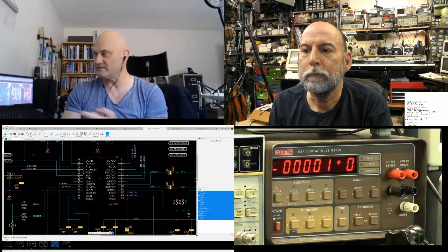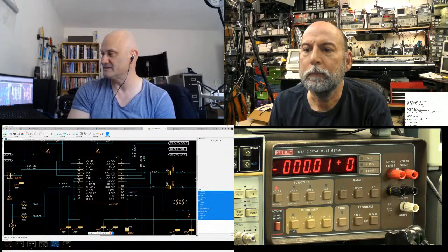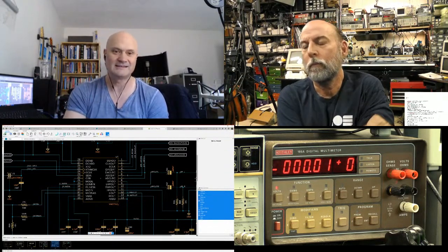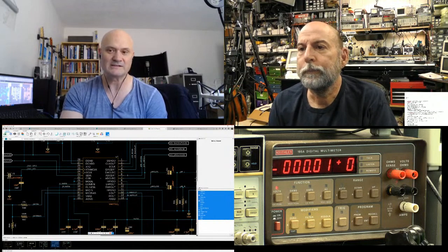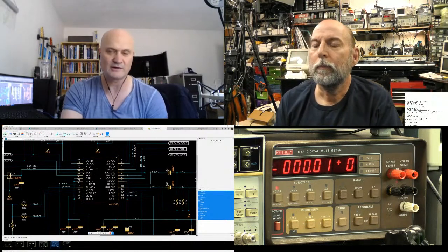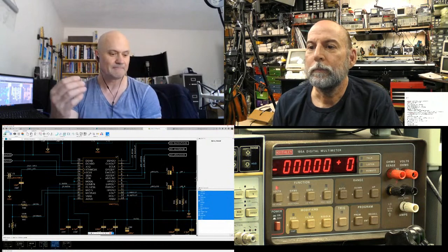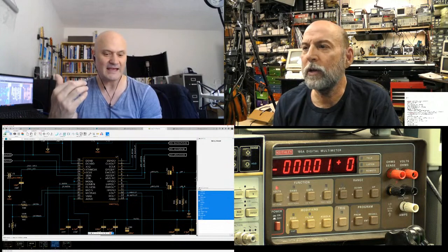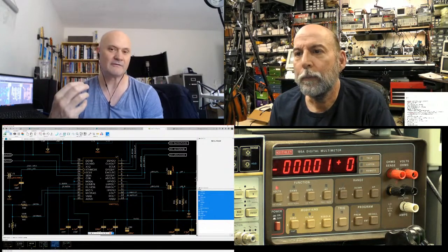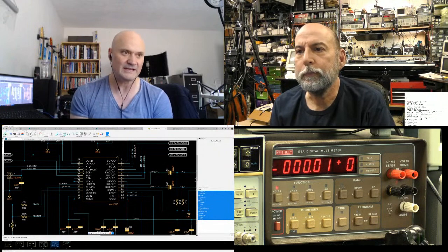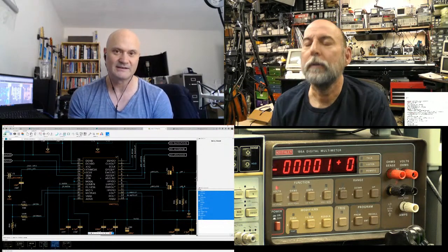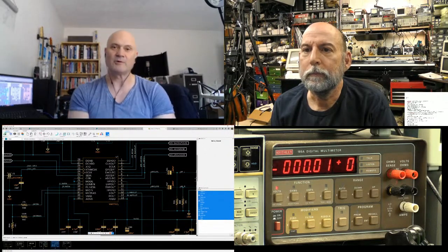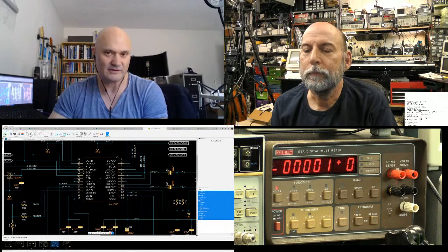But this Wolfson Micro has a separate D to A converter LR clock and A to D converter LR clock, which implies that you can have different sample rates for input versus output of your codec. So I could use this Wolfson codec and have a microphone with a telephone sort of bandwidth coming in at an 8 kilohertz sample rate for the input, but still be spitting out a 44.1 kilohertz sample rate for the output, for example.